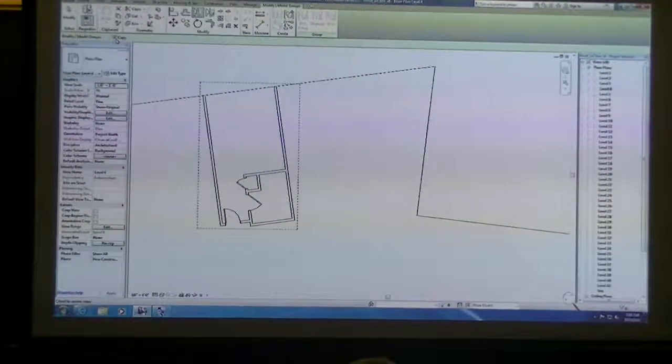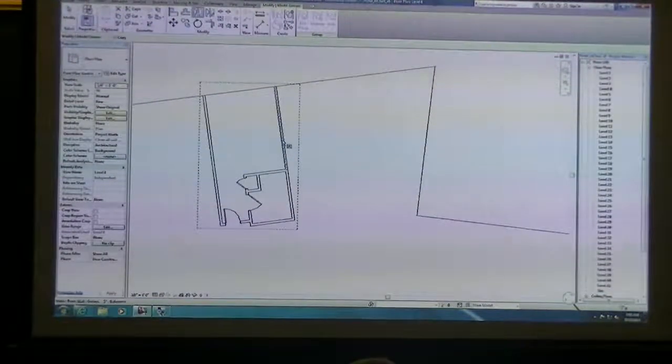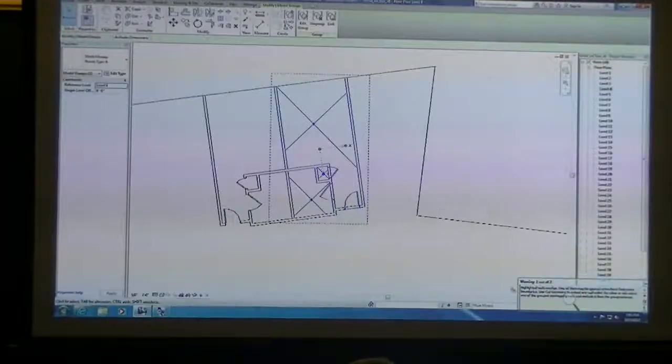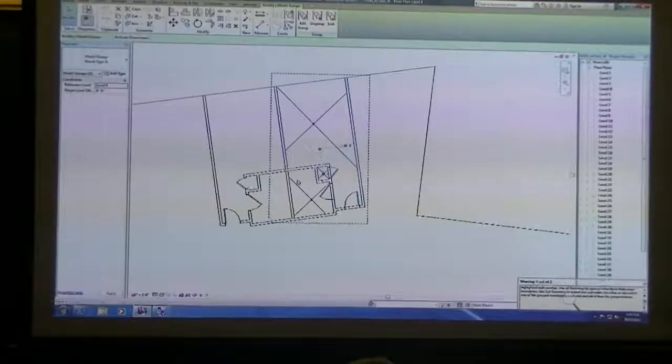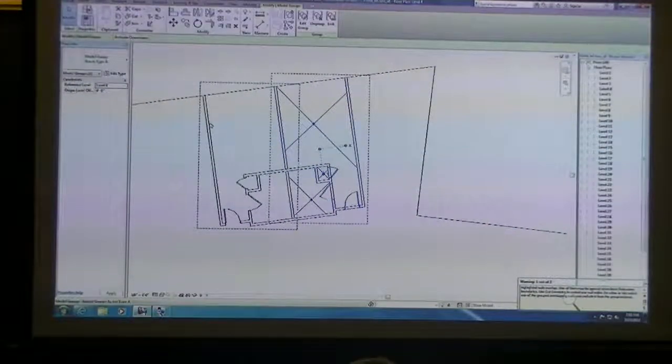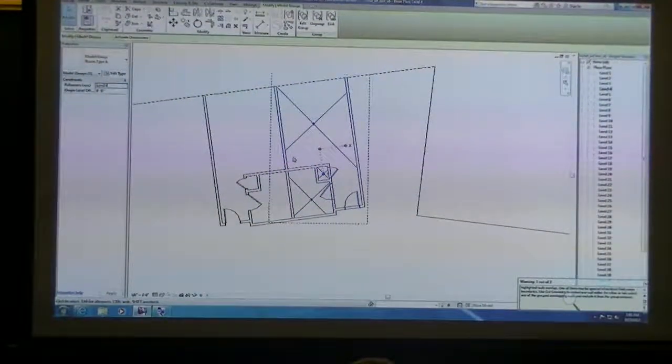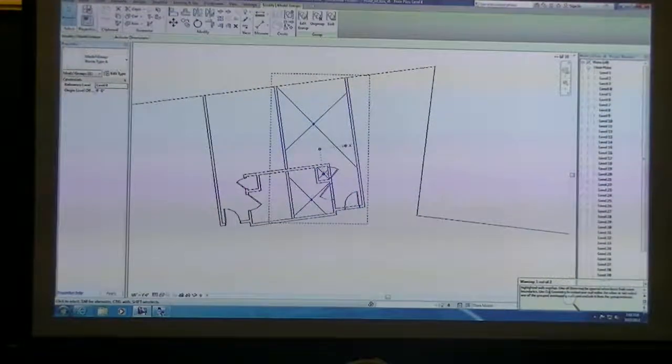And I've got my copy option shown on the options bar checked. I can just flip that, and it'll give you a warning that says, oh, by the way, you have walls overlapping. That's because I've modeled both sides of the room. Yes, we're going to have some overlap when we do this, but it's basically just telling you that there's an overlap, just so that if you get into using Revit to do some cost estimating, or try to figure out the exact square footage of drywall that you have, you might get double counting of your materials.